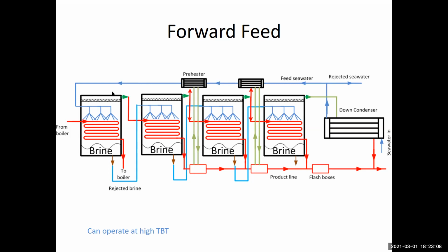But the vapor has formed here at P1. If we neglect the pressure losses, then all of this fluid inside the tubes is at a pressure of P1. So the pressure of the fluid here is P1. It is going to enter into the flash box at a pressure and temperature of P2 and T2.